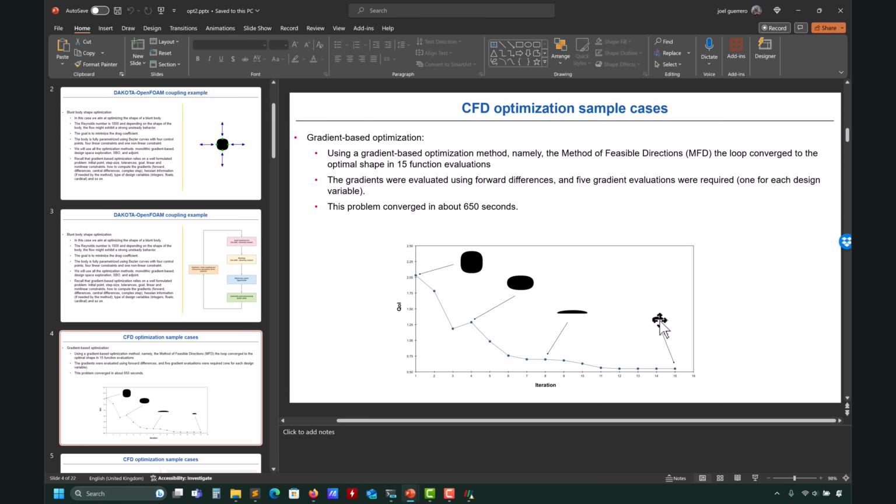But for instance, if you would like to optimize L/D, which is very important in aeronautics, this efficiency factor, this is not the best one. Globally speaking, this one will have the lowest drag, but when we look at another quantity like L/D, this will probably be the best one, because we'll have a low drag but also produce more lift, and even more if you add a little bit more curvature. So formulate your problem; this is part of the problem formulation. We also created another video with an exercise from this working case on how to compute this for L/D.